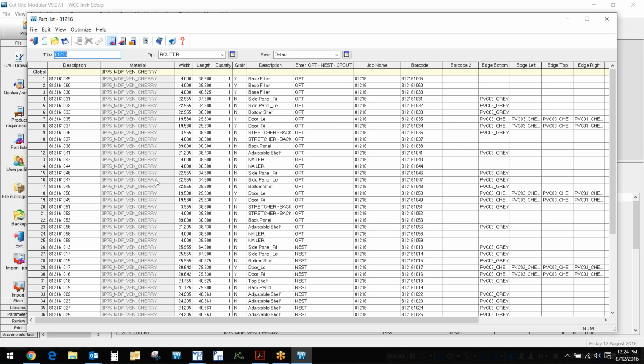Yeah, okay, so the main differences are this. When we're optimizing to a saw, we can stack boards and cut multiple at a time. However, every cut must go from one side of the board to the other. In the routing, it's one sheet at a time, but it can make paths for however the router bit can move. Okay, let me say that real quick.